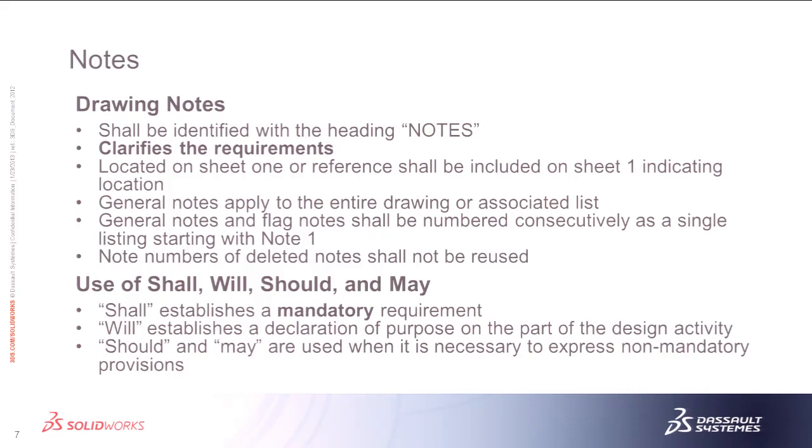Let's see. So general notes apply to the entire drawing or associated list. General notes and flag notes should be numbered consecutively, starting with 1. And note numbers of deleted notes shall not be reused. We'll say one thing on there. We have levels of drawing packages: preliminary, reference, baseline. We reuse them until it gets to the baseline stage, and then we don't reuse them again. So that's kind of an in-house practice.